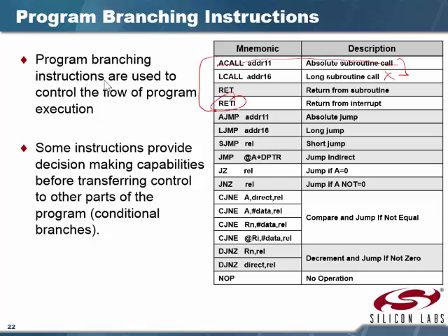The A call is a 2 byte instruction, because you've got 11 bits for the address, and the front part is for the call or the jump command, and then the other 11 bits are for the address. The long call is 1 byte for the call command and then 2 bytes for the address. So you have an extra byte there, and your code gets a little bit longer, one whole byte. Back when you only had 512 bytes or 1K for a program, that was a big deal. Now it's not such a big deal with 4K to work with.